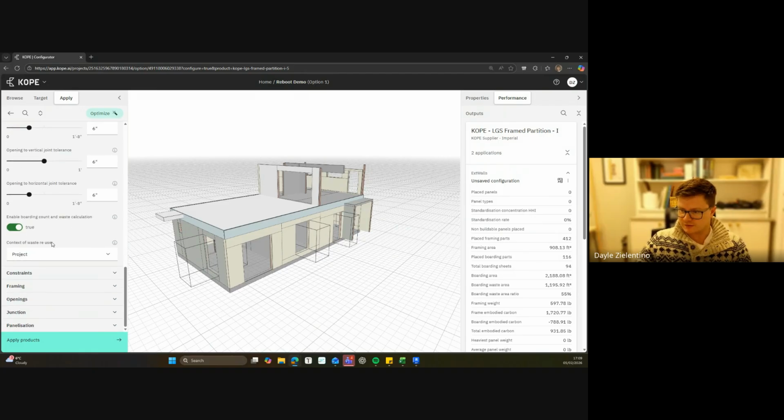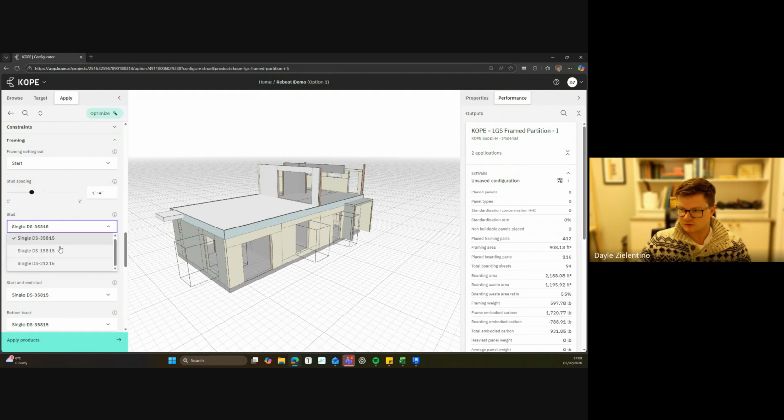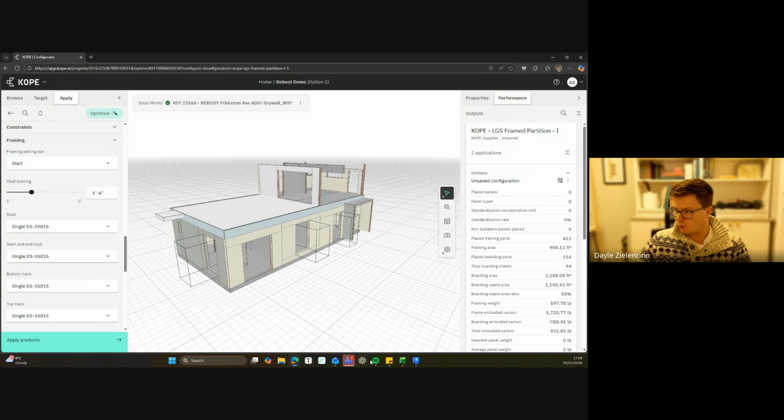Now, if we get down to framing, the same thing. So if we come to the framing, you would have what are your framing sizes and studs that you'd be using. So, you know, this is 3 inch and 5/8 on a 15 gauge, etc., etc. We have some customers that have a couple hundred options in here, of stud configuration and size and profile. In this demo, we just have the 3, but you could have all of those in between. So from what I could tell from the Revit model, you had the same stud size, I believe. It was more the ply build up on the outside that differed. And I think the gauge, so your overall size of stud didn't change. It was just the gauge that was put in through there.